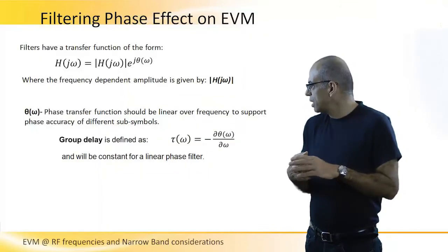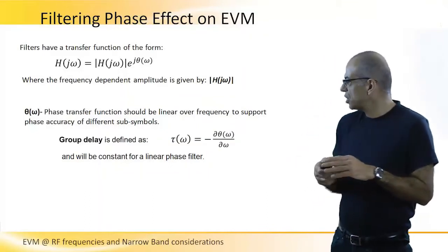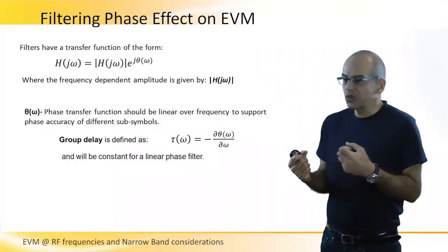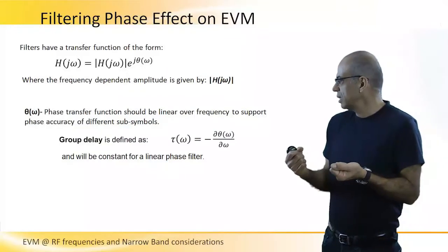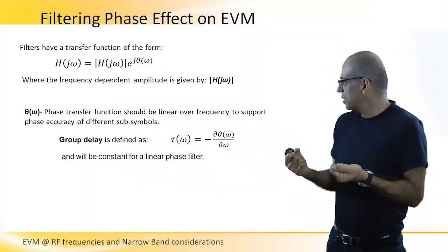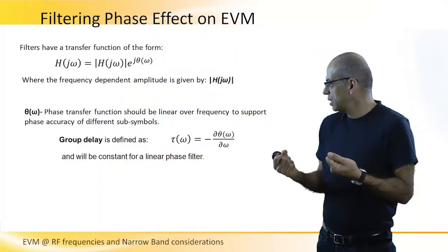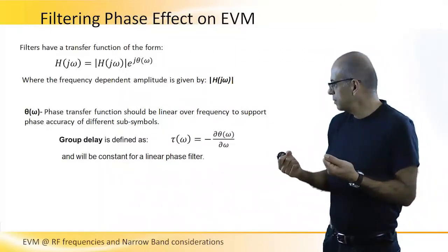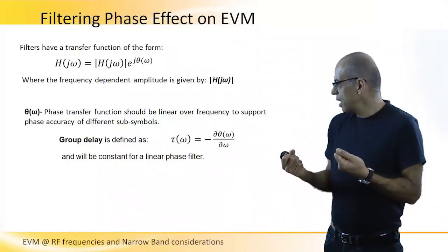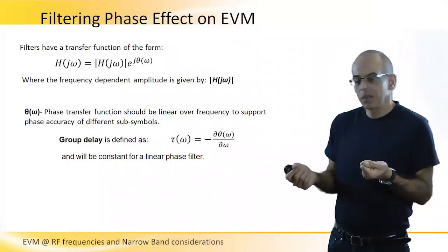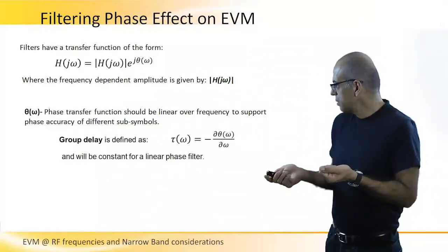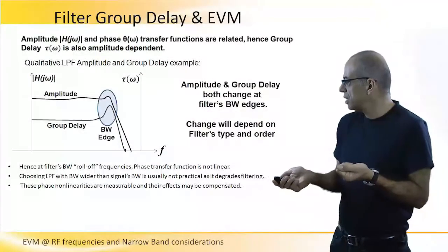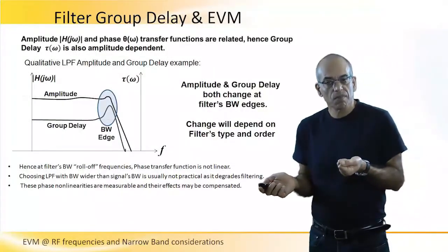And if we look at the phase part, we usually prefer to look at the derivative of the phase over omega, over the radial frequency, and to talk about group delay. And it is very well known that we expect the group delay to be a constant over bandwidths.